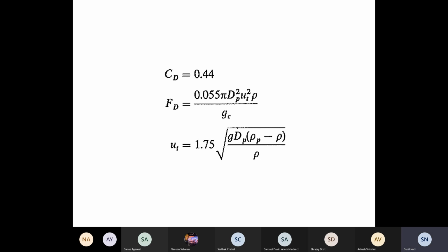See, this is a very different relationship from the Stokesian, because in the terminal velocity, the quadratic dependence on the particle diameter is now replaced by a square root dependence. So completely different scaling, right? That is a hallmark again. This half power dependence on the diameter of the spherical particle is a hallmark of the turbulent flow Newtonian region equations.